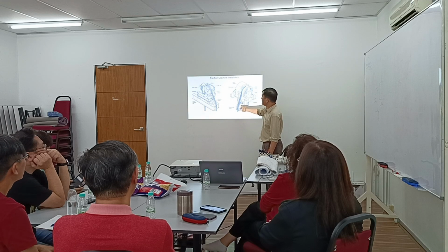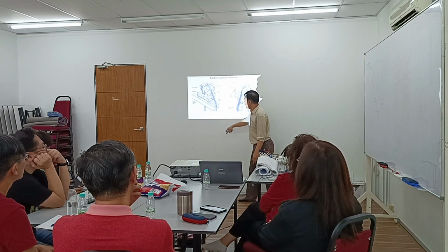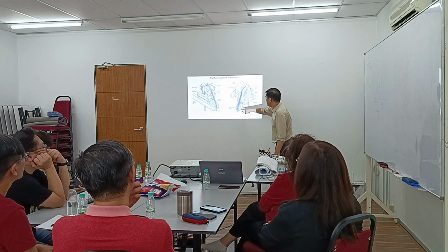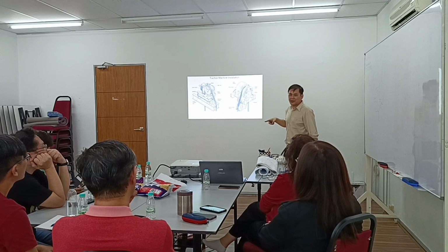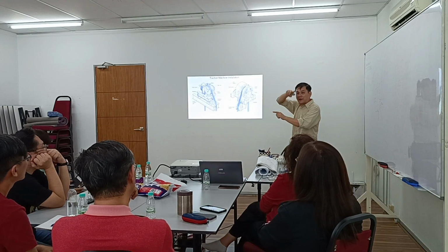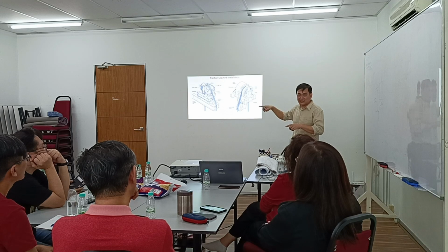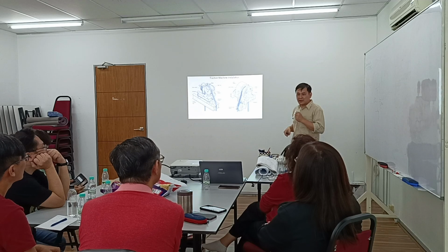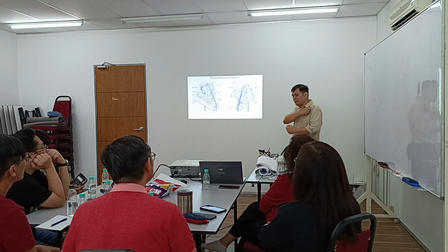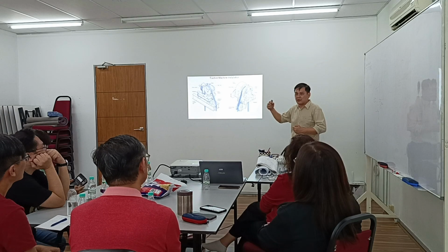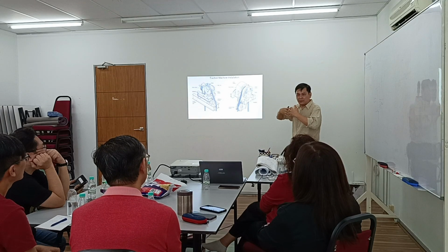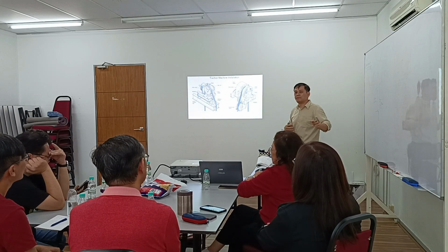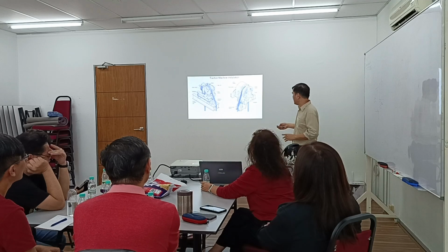So this is the double wrap system. So you see one side is the lift car, one side to the counterweight, and then this is the back frame, and then this is the so-called double wrap sheave. Double wrap means the rope you wrap twice. Why we have this kind of arrangement? Because it's a high speed. When the speed is too high, the movement of the rope can simply be faster than the sheave. So we want the engagement between the sheave and the rope always be intact. Otherwise, what will happen? Slip. That is also a reason behind it.